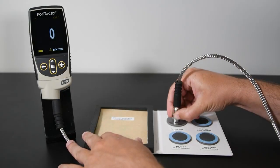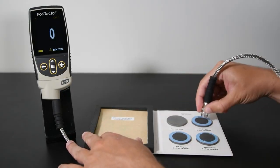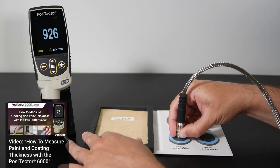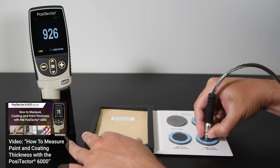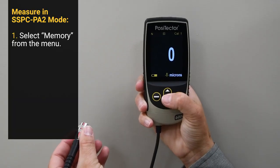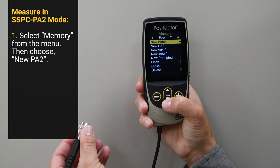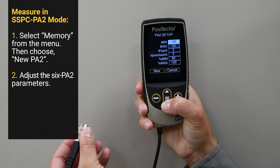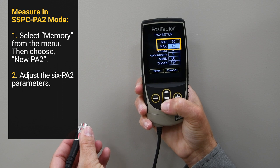First, ensure that the instrument is verified and adjusted for the substrate geometry. To learn more about getting started with the PosiTector 6000, view the video linked in the description. Once the instrument is ready to measure, select Memory and then New PA2 from the gauge menu. 6 parameters are displayed. The minimum and maximum coating thickness should be set according to project specifications.